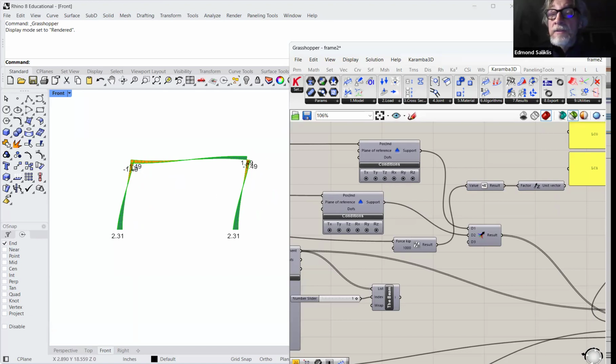Half of that moment. But now the penalty, of course, the energy has to go somewhere. The penalty is that we have to restrain the moment at the base. And if that moves a little bit, then it's not restrained.